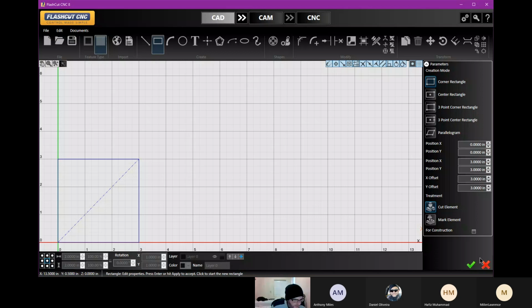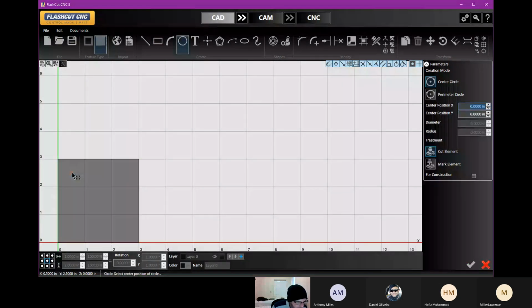We'll go in a 1/2 inch by 1/2 inch, and we'll put, yeah, that works. We'll put a 1/2 inch hole. Okay. We'll do this in all 4 corners. So we count 2 blocks over, 2 blocks down, give it a click, and drag it out to a 1/2 inch.